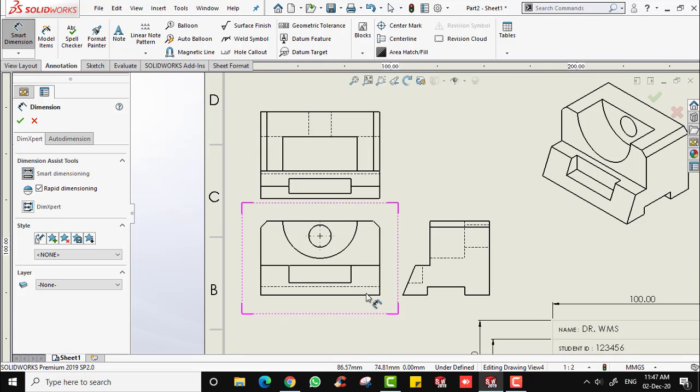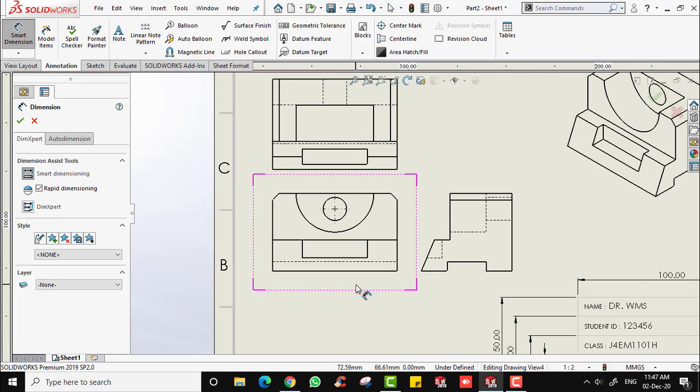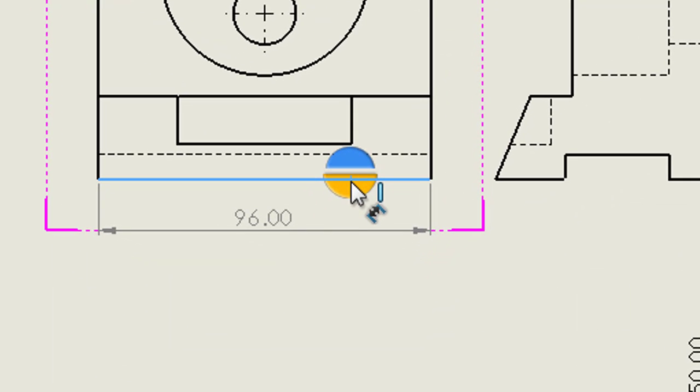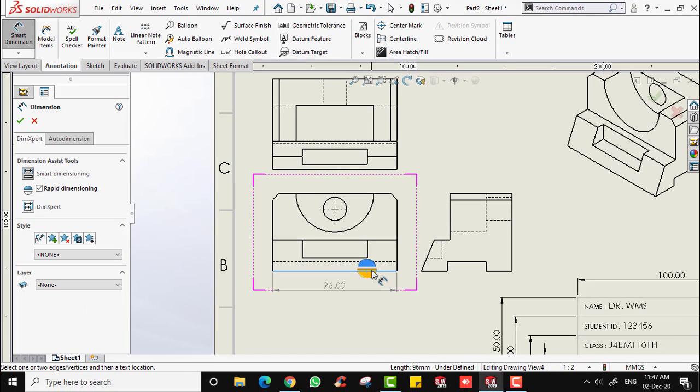In this drawing, I'm going to start with this parent drawing. When you use dimensioning in this drawing document, you will notice there are two semicircles over here. That is a recommended space to put the dimension. I often use this to ensure neatness in dimensioning, as it basically sorts the dimension for you.